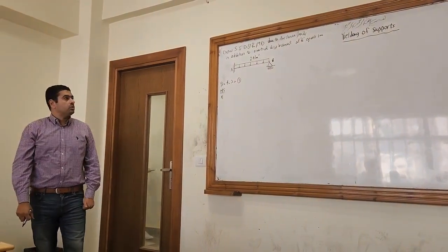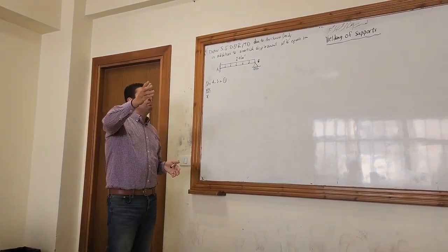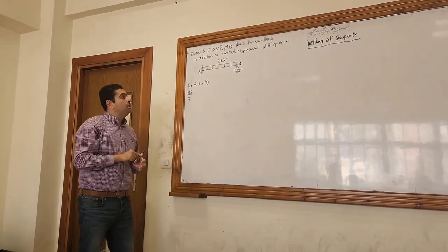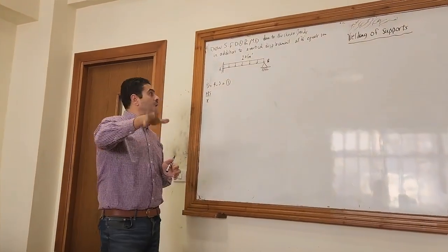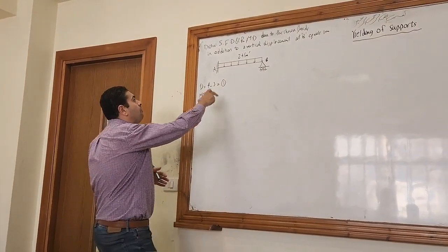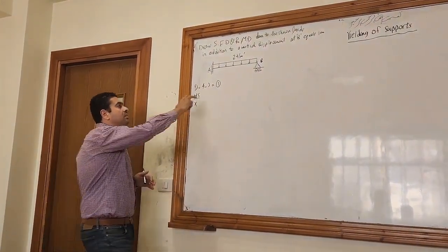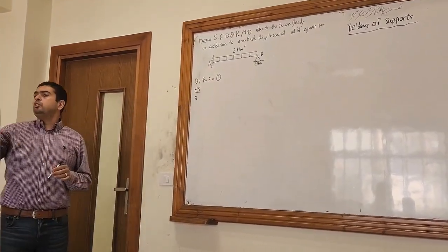What if it's a regular example? They can say I remove the roller support at B, so the main system will be fixed free. And then Abdullah will say, no, I remove the moment at the fixed support, so the main system will be hinged roller, simply.